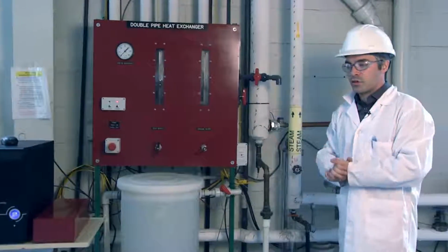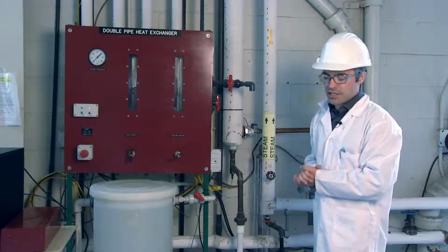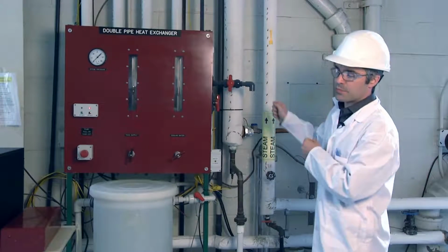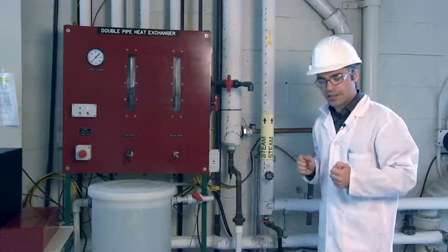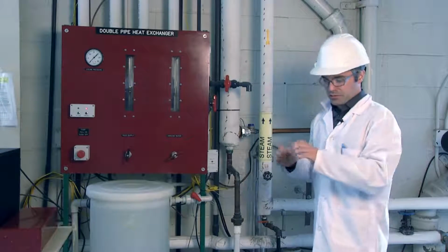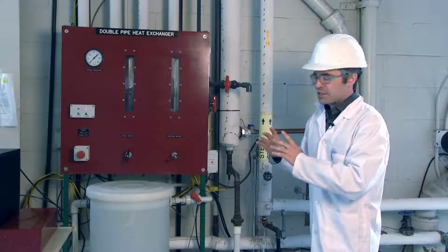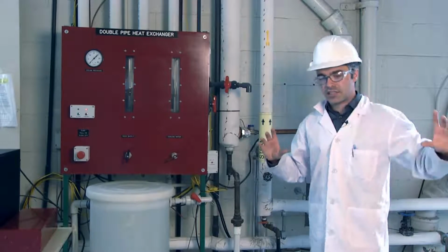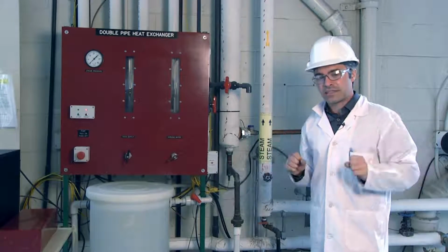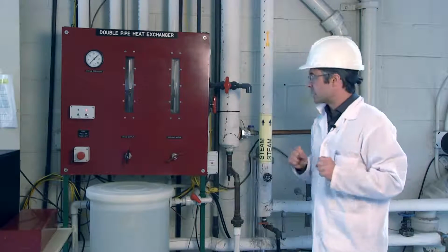Once you have the total energy balance for the system, you'll have the total changes of temperature, you know the properties of water, and you know the driving force is that difference in temperature. You know how much energy is transferred, so you'll be able to find the overall heat transfer coefficient experimentally.